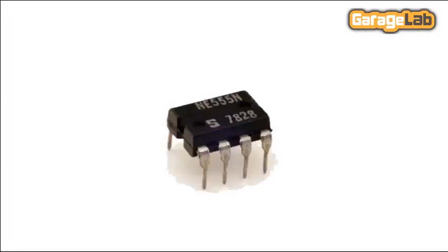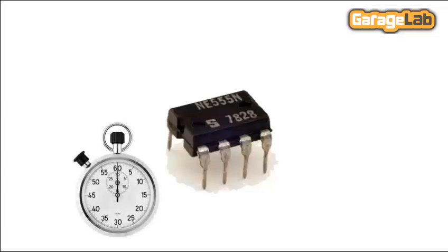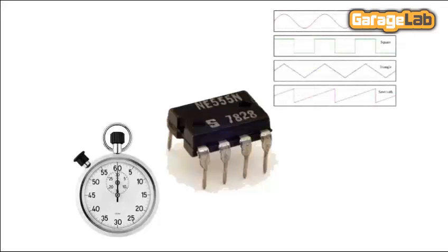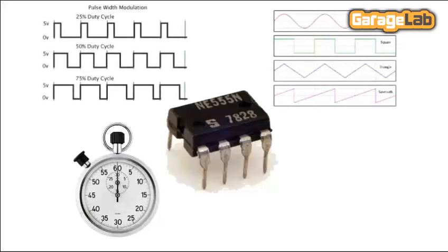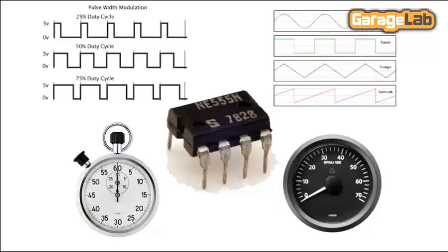The key part of our prototype is the IC555, famous among the designers and electronics lovers. Its fame may be associated with its easy usage and its ability to generate short and long timing, not to mention its low cost. It has numerous applications. Among them we mention the timer, the oscillator, the PWM generator, and the tachometer. Our prototype uses it as an oscillator.